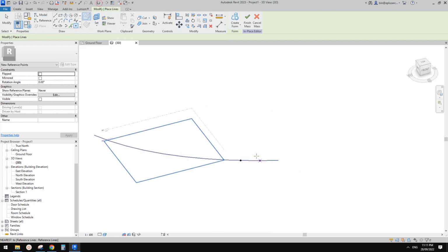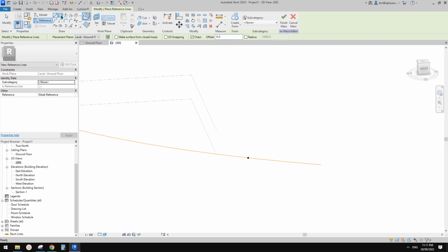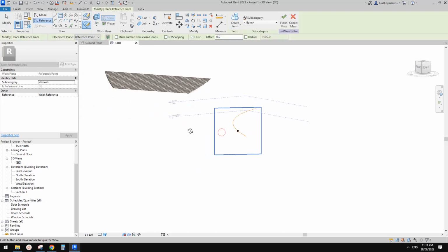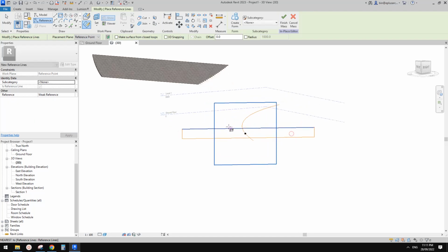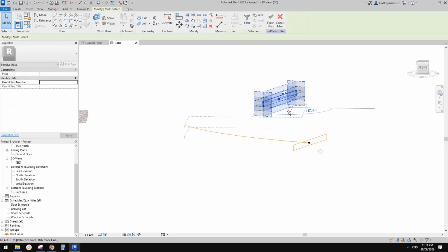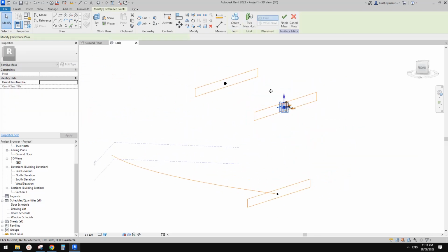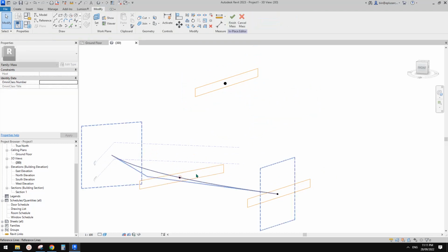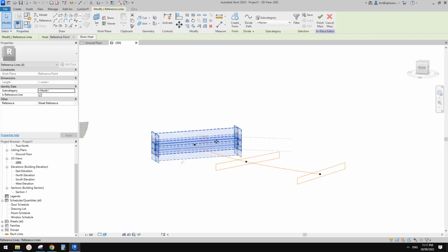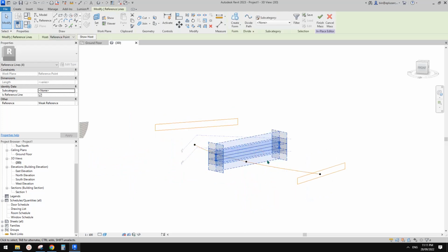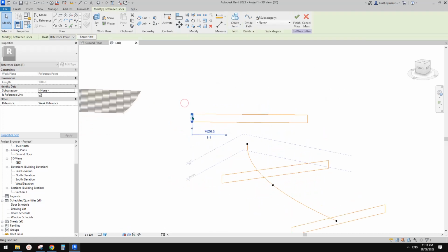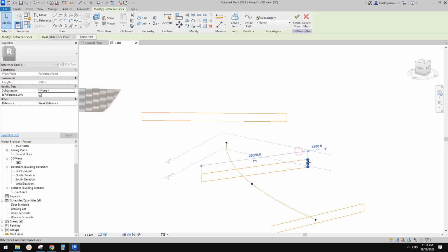Let's go to 3D view. Then we can place a profile, use draw on work plane, and set the work plane onto this point, so we can create a profile of this mass. Okay, so let's drag this to hit this end, and copy this, Ctrl+C, and paste another two. So put one in the middle, put the other one at this end, and then we can just move this up a little bit. I think you can also increase the size of this one, so for example, maybe move this one.